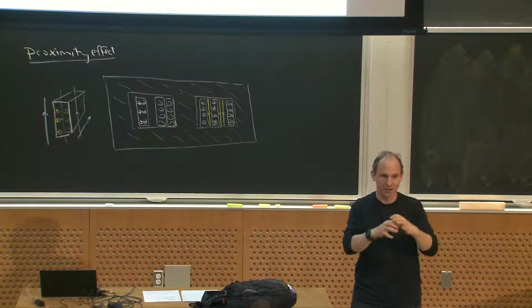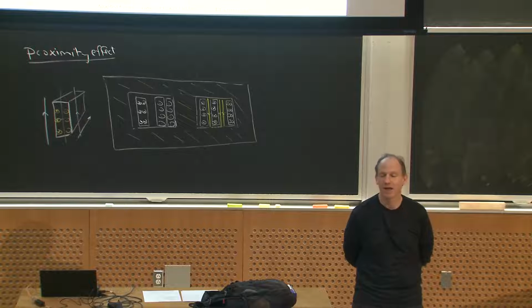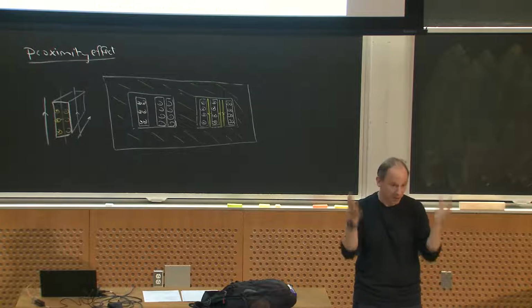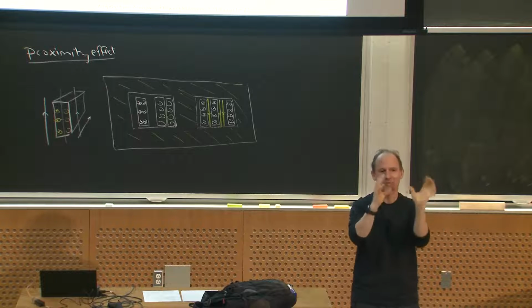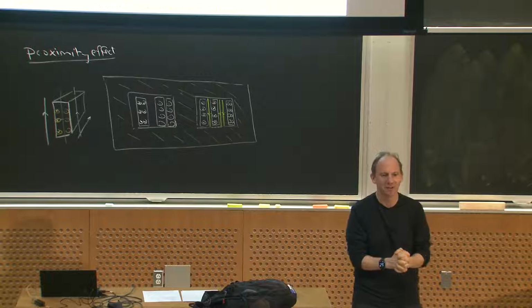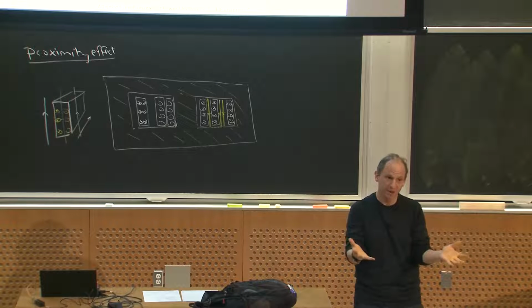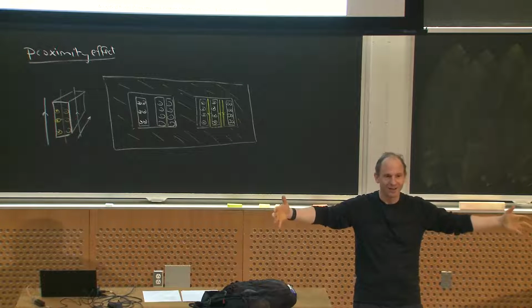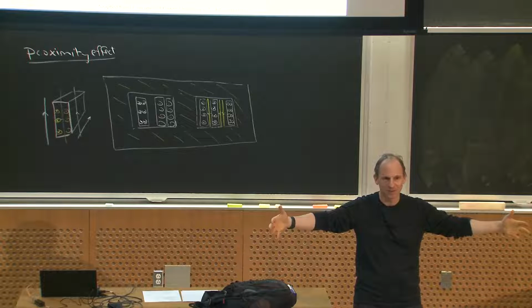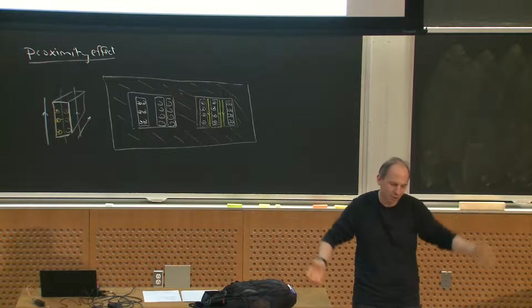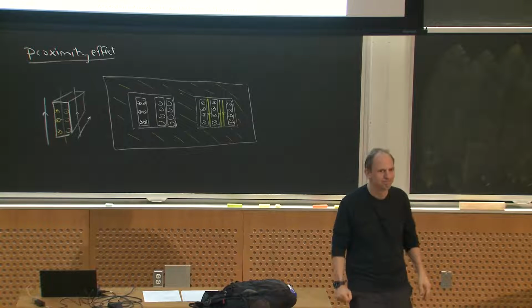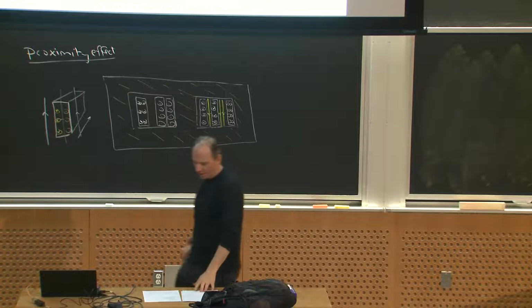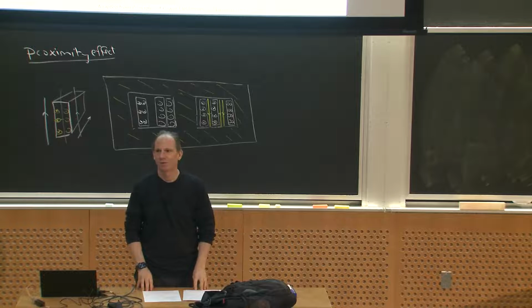yeah, well then you're going to have to strand and insulate your wire, Litz wire. And so if you look at things like steam turbine generators, they do use Litz. Their bundles are like this, but it's big compressed chunks of copper. So this applies at any frequency if you're carrying enough current. If I'm building a 60 hertz transformer that's carrying an amp, my conductors are naturally going to be much less than the skin depth, and I wouldn't even think about it. Okay, so that's winding loss, right?